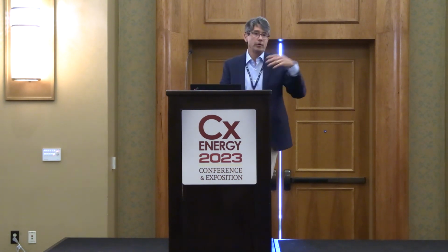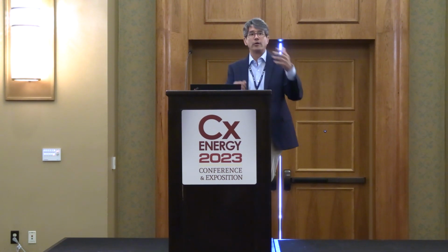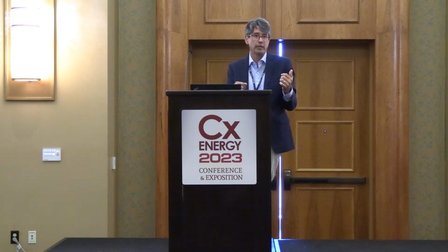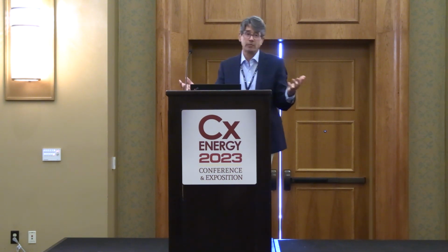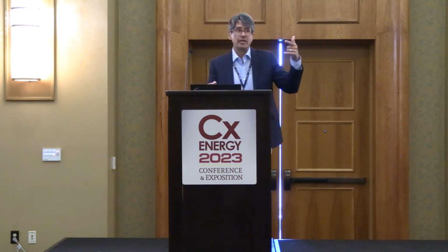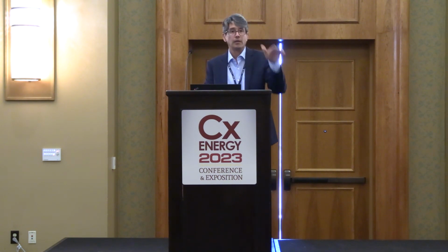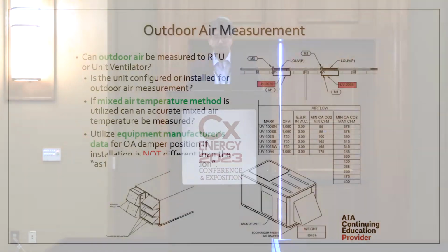So you have to get very creative in scenarios of putting the system into 100% outdoor air and try to set some things up of what can I do for measurements, and then try to get damper positions that might correlate. Variable air volume system becomes very difficult because then your fan speed's changing too. So you can get into some very difficult situations to try to prove up outdoor air, but if we're looking at those drawings ahead of time and tell everybody, hey, here's your problem, what can we do? Then we can try to address it up front.